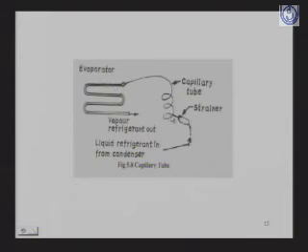Now depending upon the size of the orifice and the length of the capillary tube, we can change this. If the length is more and the orifice is small, the pressure drop is more. If it is otherwise, the reverse will take place. Now this is the simplest mechanism of expansion device.